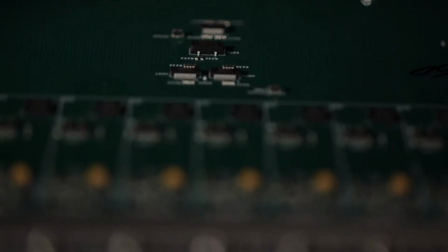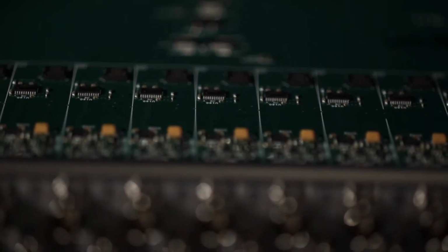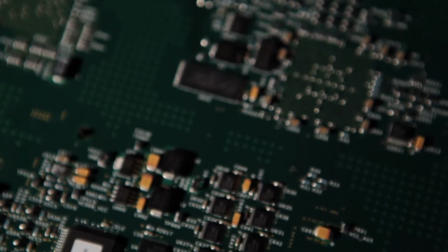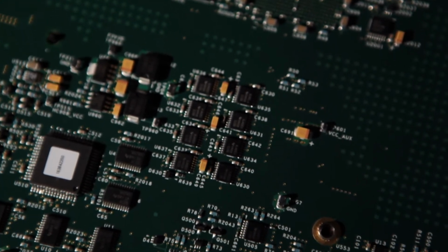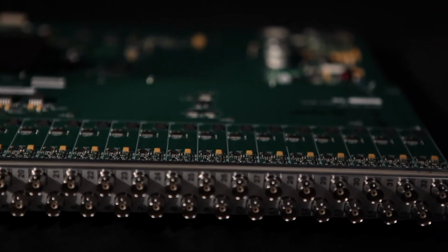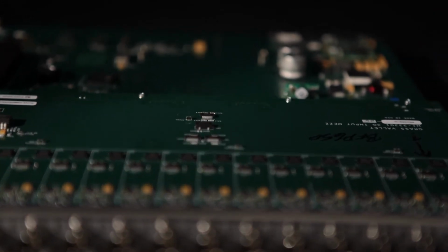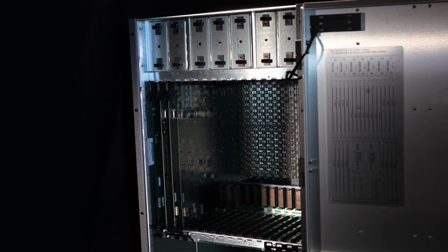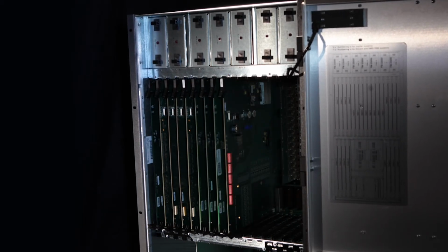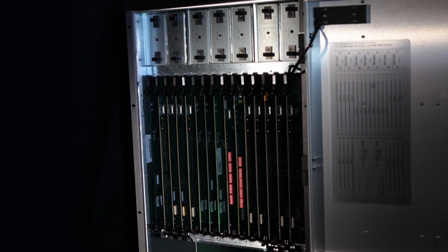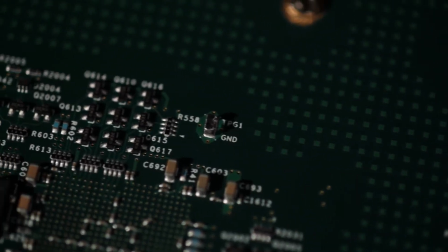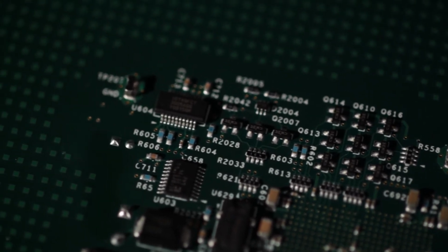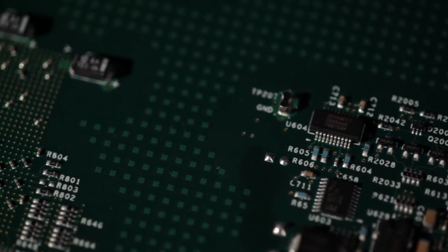But for best performance, we use balanced differential signal pass throughout the system from the input equalizers to the output cable drivers. We also use special circuit board materials that reduce high-frequency signal losses. After selection of the best components and materials, careful attention is still required to provide good signal integrity. We have designed the system to minimize the interconnection distance between the matrix modules and the input and output modules. The longest signal traces on our high-speed backplanes are about 35 centimeters long, with most of them being much shorter. Coupled with careful circuit board layout, this gives us improved signal integrity.